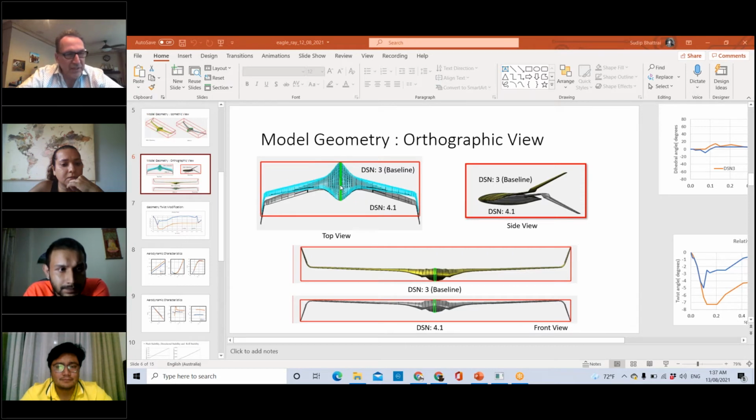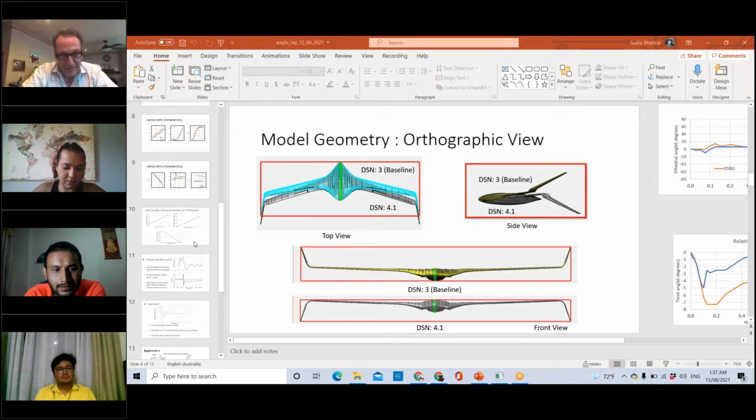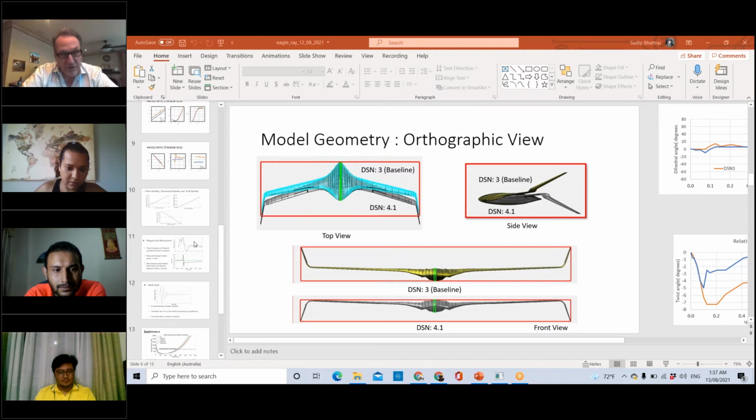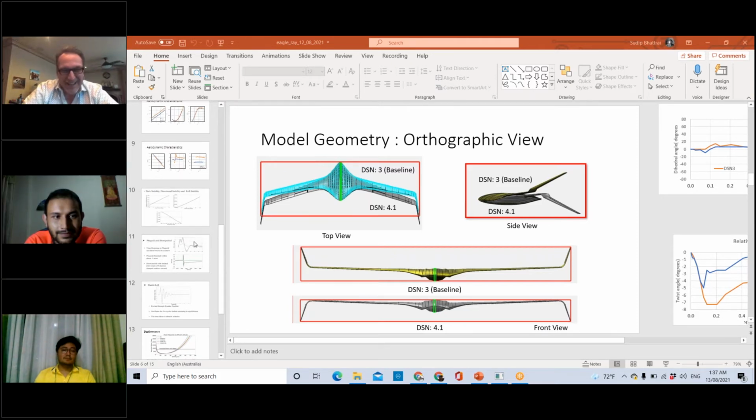So describe to me a little bit your experiences hand flying the airplane. You said you could really see the Dutch roll. It was, and it looked like it was taking, what was it, like 3 cycles to half amplitude or something, which is pretty lightly damped. Yep. Dutch roll is often lightly damped. Pitch damping looked awesome. And the phugoid, of course, if it's a clean airplane, it's going to be that way.